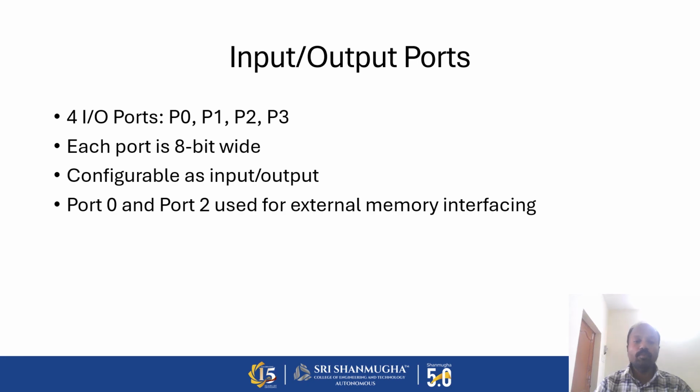Input or output ports: we have 4 I/O ports, port 0, port 1, port 2 and port 3, using which we can communicate with the 8051. Each port is 8 bits wide. You can see that 8 pins are used for each port. They are configurable as input or output, so we can configure a port as an input port or an output port based on the selection. Port 0 and port 2 are used for external memory interfacing. The main purpose of ports 0 and 2 is accessing the external memory.